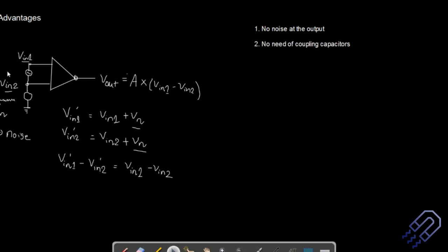And here I'm not showing you whether it's an inverting or a non-inverting terminal. But in general, if you have a signal like this, and I'm just having one output here, you're going to have an output where the signal will definitely be amplified, depending on the value of A. Another day I told you that the A value ranges up to about 10 to the power 5 for many amplifiers. So it's not that you can have 1 volt and amplify it to 10 to the power 5 volts.